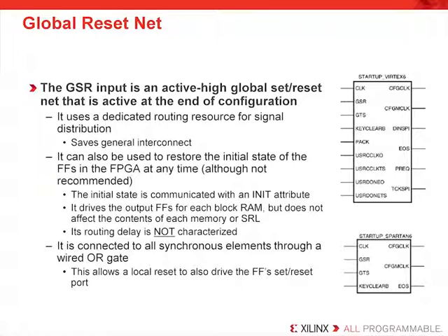It can also be used to restore the initial state of the flip-flops in your FPGA at any time, even though this is not recommended. In this case, the routing delay associated with the GSR is rather slow, and it's not characterized. So using this to reset at any time is not recommended for that reason.